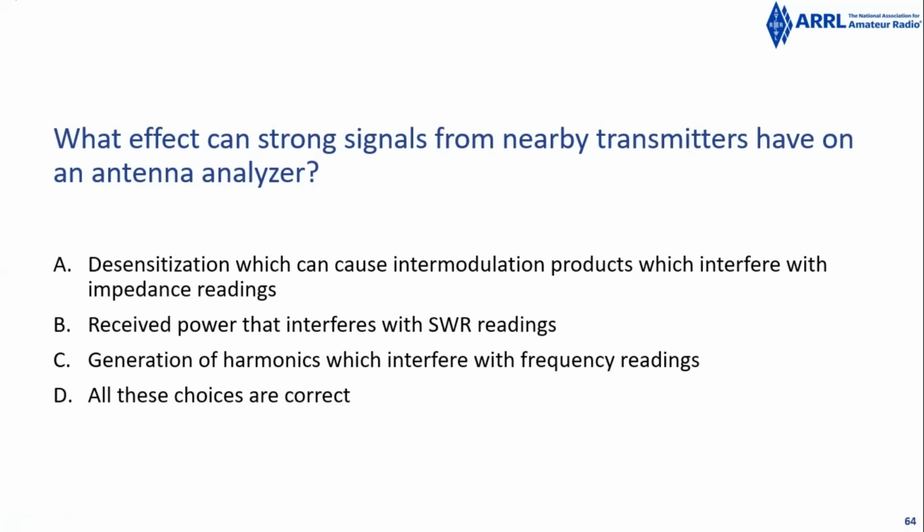What effect can strong signals from nearby transmitters have on an antenna analyzer? They can desensitize it. Receive power that interferes with the SWR reading. So if I'm trying to measure something locally and Jason's living next door to me and he powers up his kilowatt amplifier, he can affect my little SWR meter.